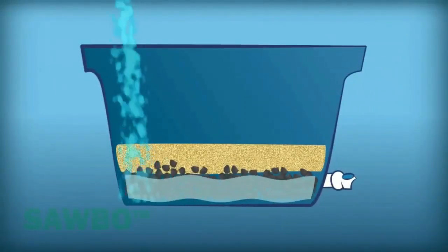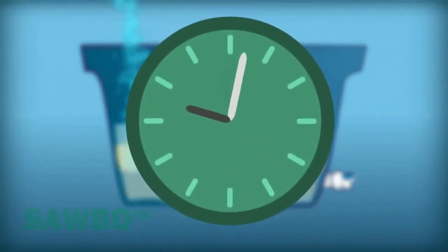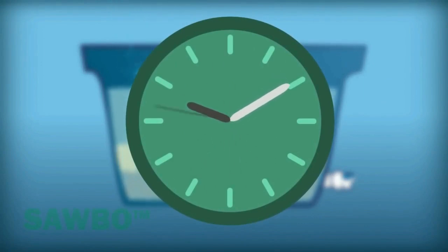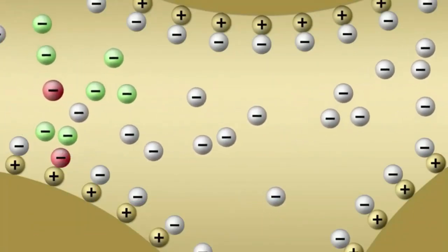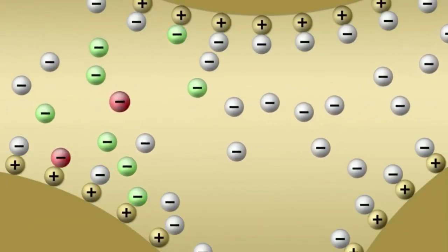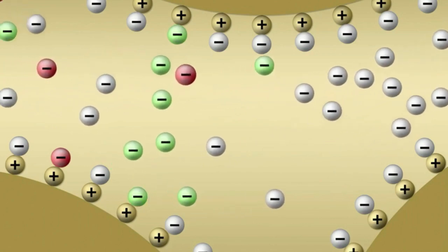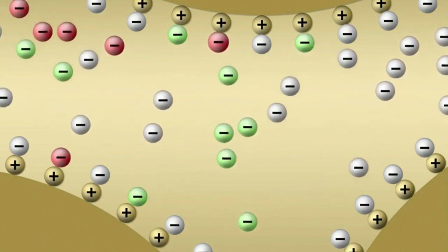How stones and minerals cleanse water chemically and physically. Adsorption. Activated charcoal and zeolites operate primarily through adsorption, attracting and holding certain chemicals at their surface. Ion exchange. Minerals like zeolites exchange one ion at their surface for another in the water, effectively removing harmful contaminants and replacing them with benign ones.